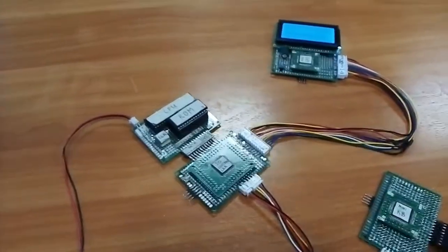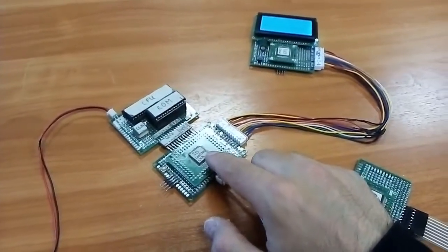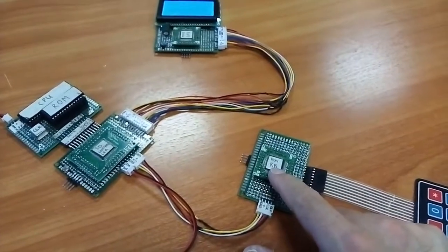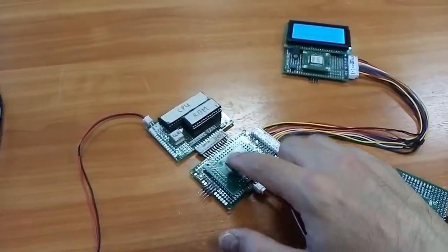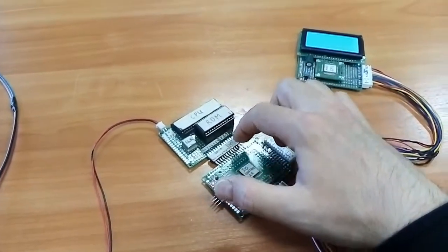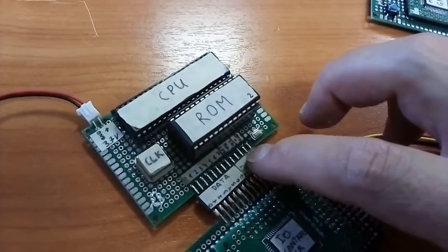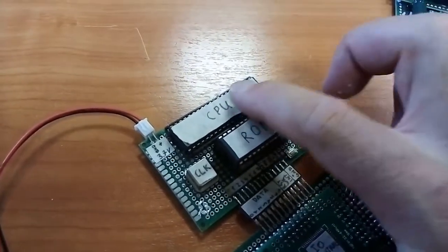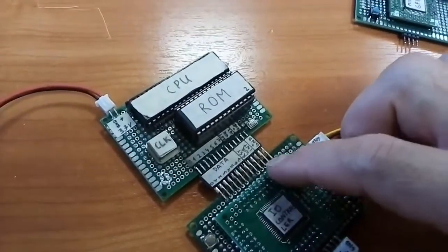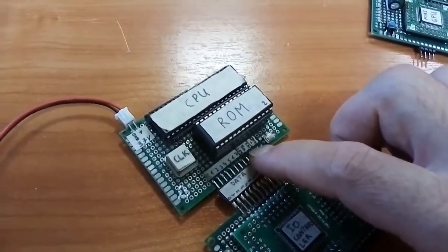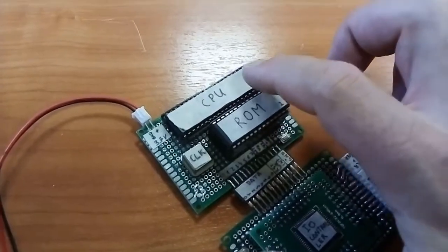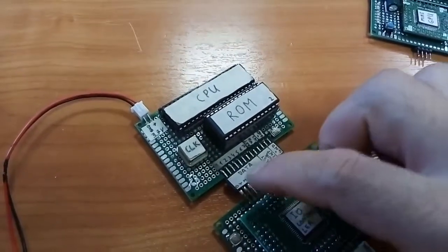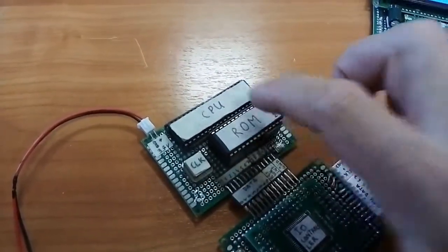You see the CPU was in waiting state, waiting for the key to be pressed, and when the key was pressed, the key code went here, and from here a signal went to interrupt the CPU. That's the interrupt pin that we didn't touch in the previous tutorial. This pin is used for the CPU to pull low. Then the CPU understands that it needs to be interrupted, and it reads from the data bus a byte of data telling where to jump in memory.